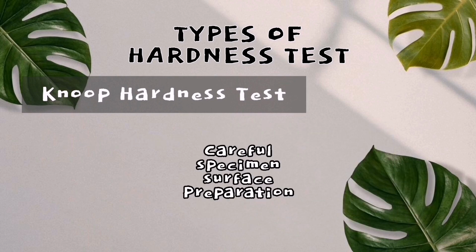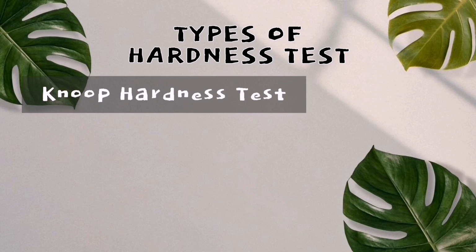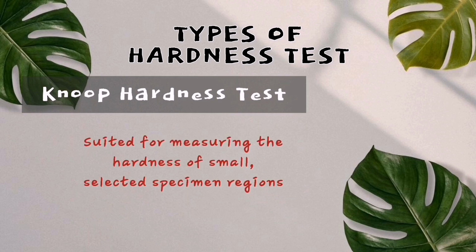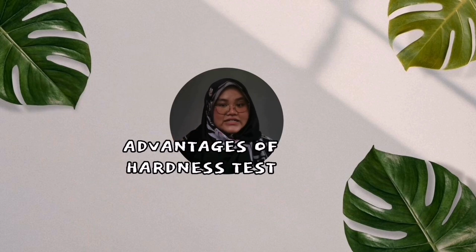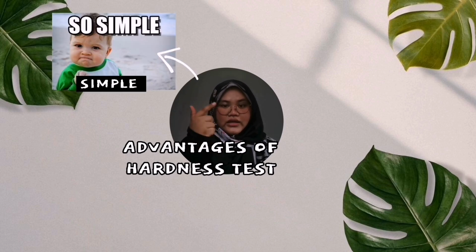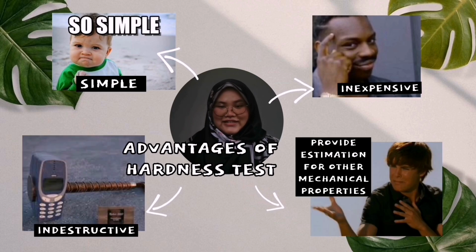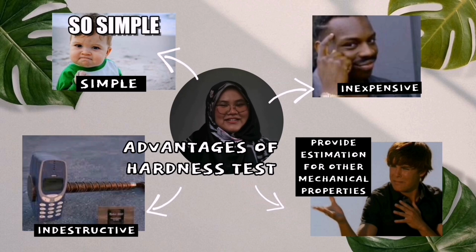Careful specimen surface preparation like grinding and polishing may be necessary to ensure a well-defined indentation. It is suited for measuring the hardness of small selected specimen regions. What is the advantage of this hardness test? Well, this test is simple, inexpensive, non-destructive, and also provides an estimation of other mechanical properties.